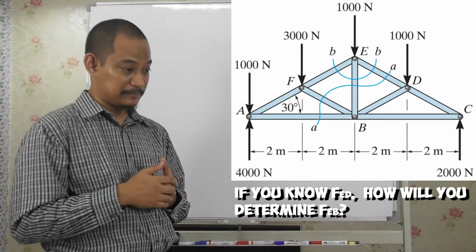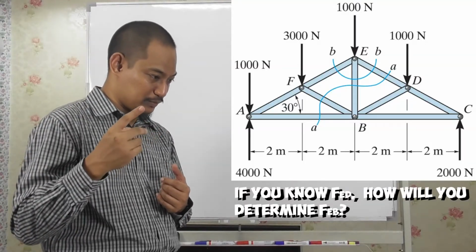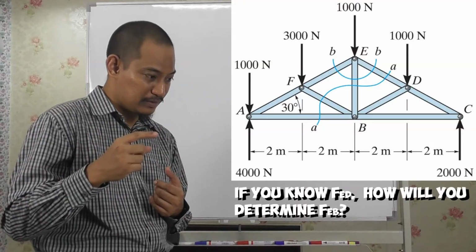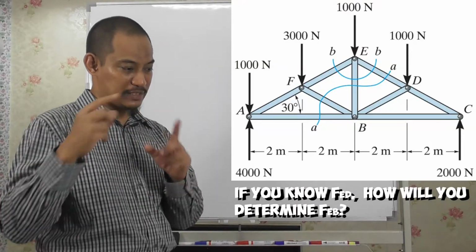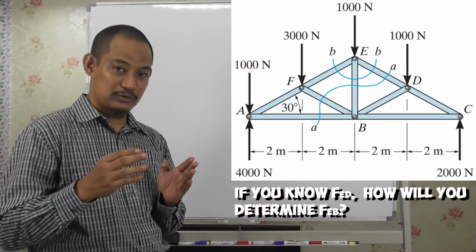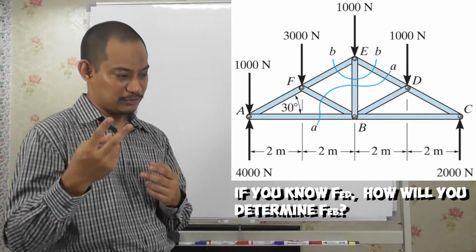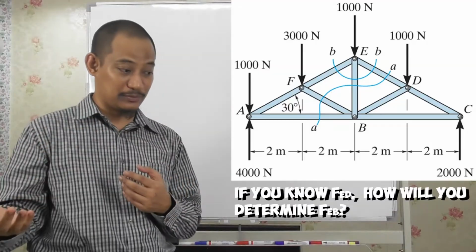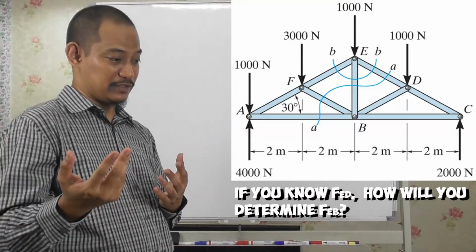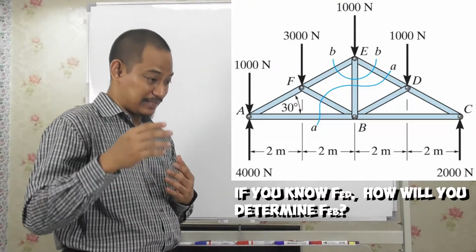That is interesting. If you cut BB, right, so you have 3 unknown, right? FE, BE and DE. So you have 3 unknown and you solve for Fx and Fy. Can you solve it? Now, sorry, you have 2 unknown, because ED you already know, right? So you actually have 2 unknown and 2 equations. You can solve actually, right? So B is possible.